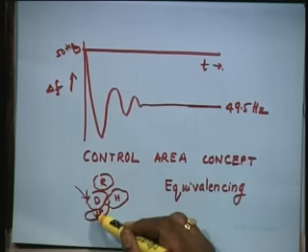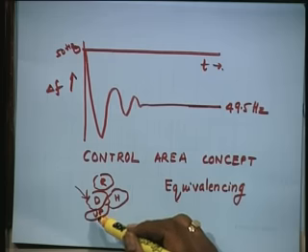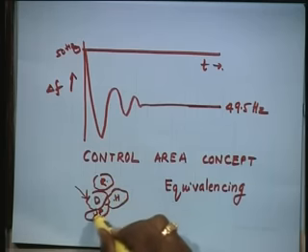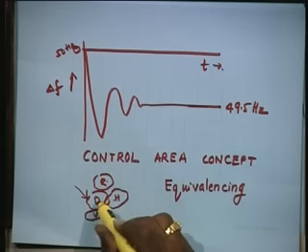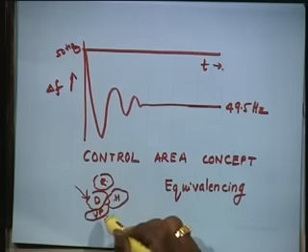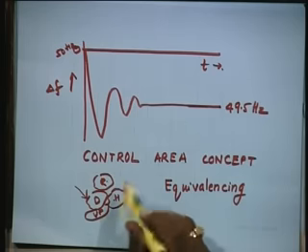So, that becomes an equivalent, reduced order system, and the number of buses is reduced from 100 to maybe 20, and it is easier to analyze a 20 bus system. Why? Because if something goes wrong drastically in Rajasthan, Haryana or UP, definitely the effect will be felt in Delhi. So, we must analyze these 3 boundary states.